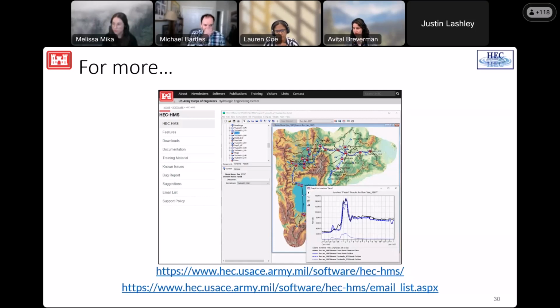All right, question from Davis. Do these disaggregation tools augment or work alongside the storm transposition work that Greg has presented on before? Good question. I remember being pumped and saying we should do this, and Greg had me slow down a bit on that one. For right now, let's keep those separated. But we could investigate that in the future, possibly to build a bigger storm catalog. AORC offers a really nice period of record for that specific purpose, though. Even though we talked about it as being somewhat limited in that you can't simulate old events, older than 1979, it does offer a very nice length for computing a storm catalog for use with the SST method.